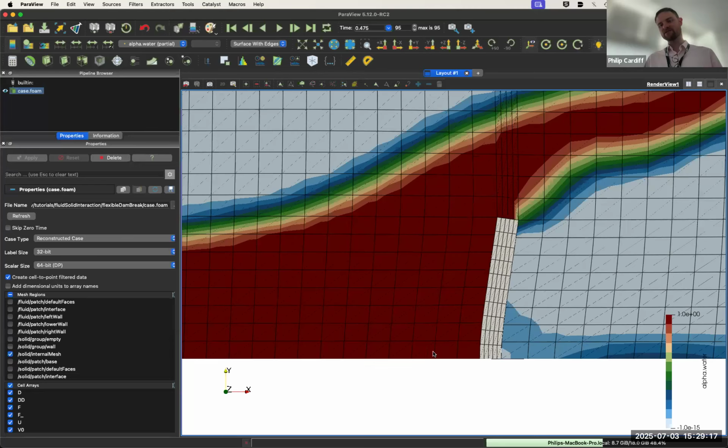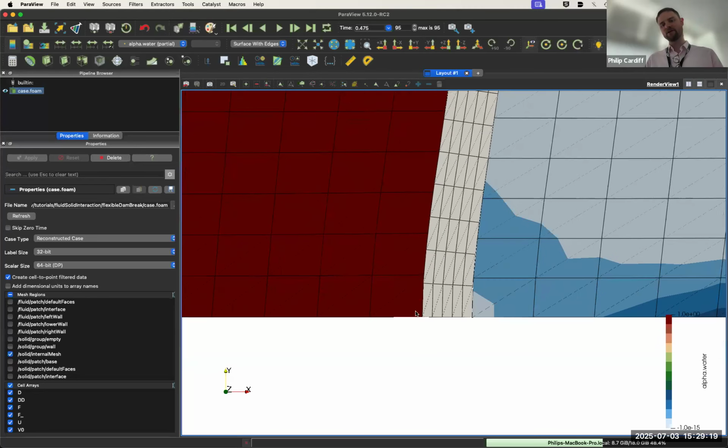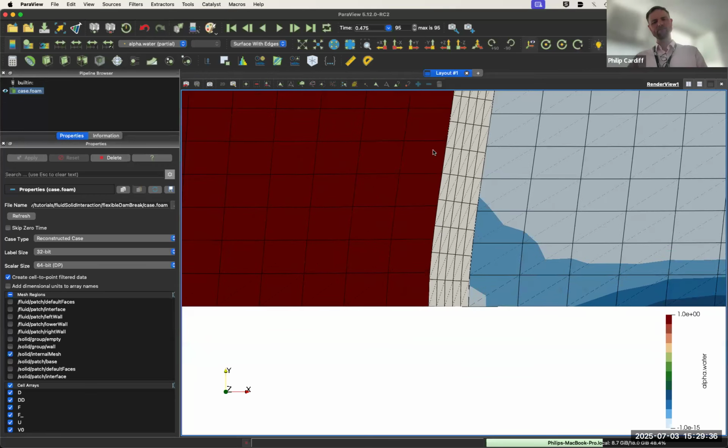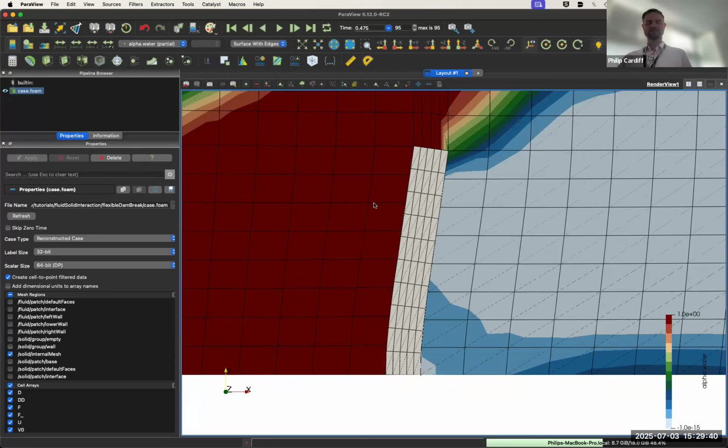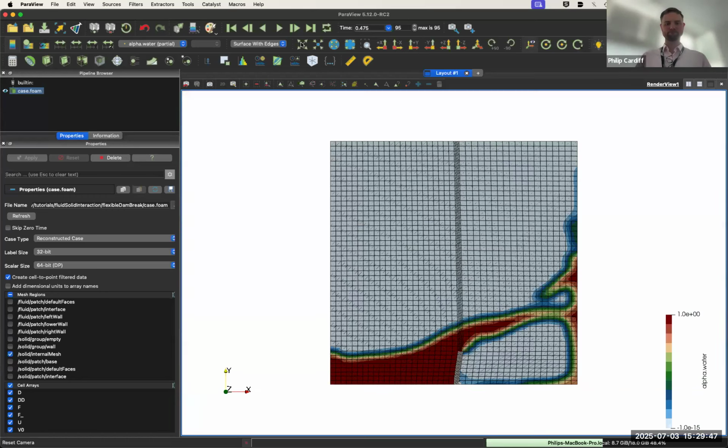Also in this case, just to demonstrate it, you can see the solid and the fluid are not conformal. So we have a wrapper that essentially sits on top of AMI. We just explicitly use AMI to map, or GGI if you're in foam-extend, or we just have a direct map, which is the same as what multi-region foam is using. So this just shows how it works. There's RBF implemented from an old port, but the current implementation is not so efficient for larger interfaces at the moment.